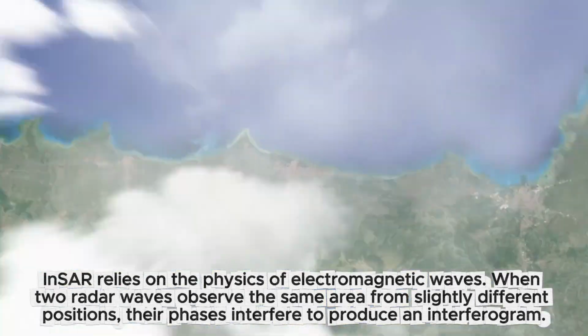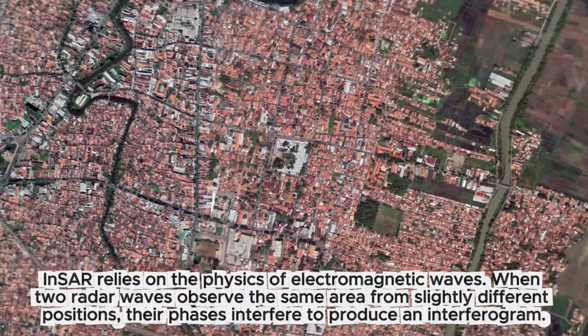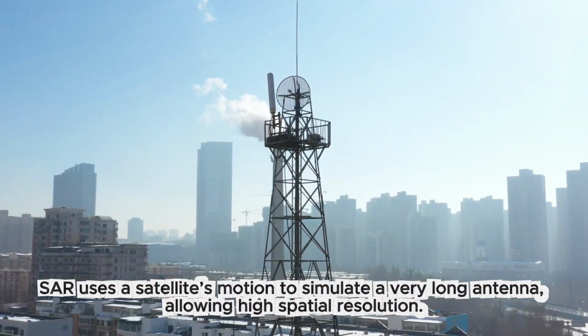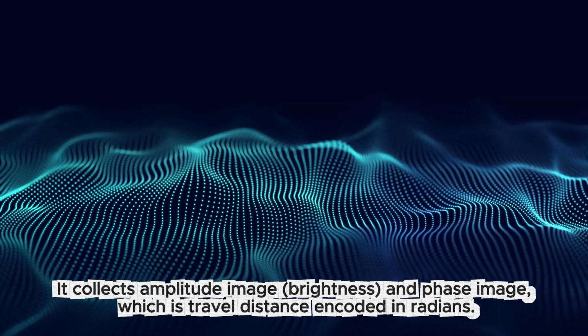InSAR relies on the physics of electromagnetic waves. When two radar waves observe the same area from slightly different positions, their phases interfere to produce an interferogram. SAR uses a satellite's motion to simulate a very long antenna, allowing high spatial resolution. It collects amplitude, which is image brightness, and phase, which is travel distance encoded in radians.